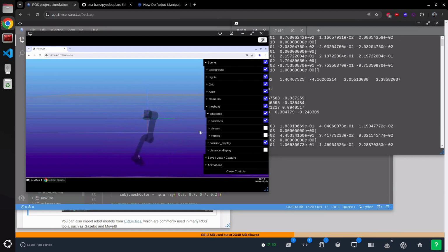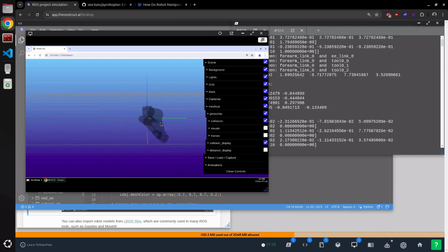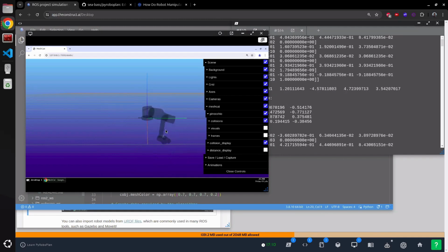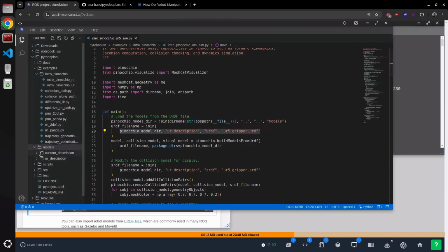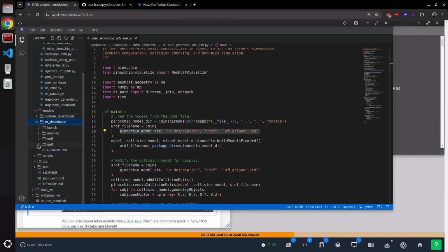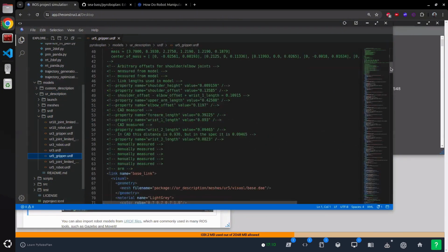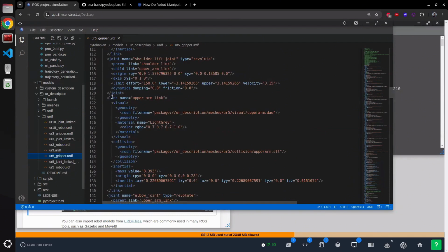And there's also, sometimes, the arm will cross itself, and you'll see some red displays showing the parts that are in collision. So what I'm getting to is that when you're working with these models, you're usually loading from these URDF files, whether it's in these libraries or things like Gazebo or MoveIt, where you have this robot, where you've defined things like links with visual geometries and collision geometries, and the tool can kind of ingest that as well. So that's my as-quick-as-possible crash course to robot modeling.